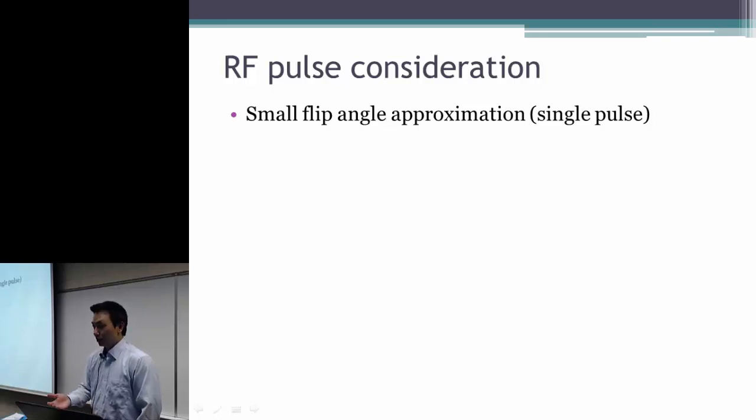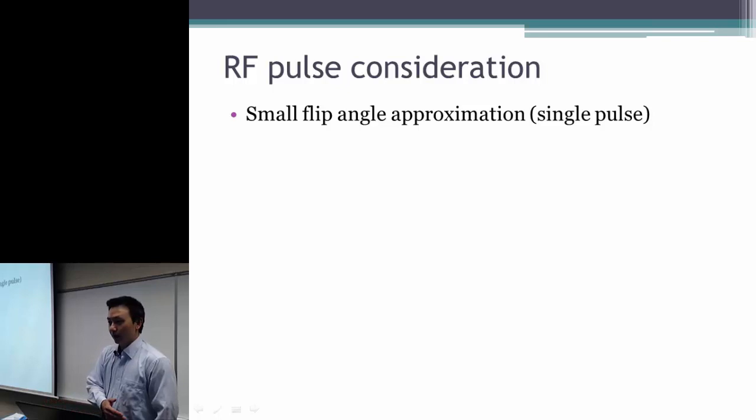So we need to use more advanced design tools to design a large flip angle. That's why we are seeing all those different types of RF pulse, like the adiabatic or Shinnar-Le Roux (SLR) RF pulses. Those are mainly developed to address this kind of problem.